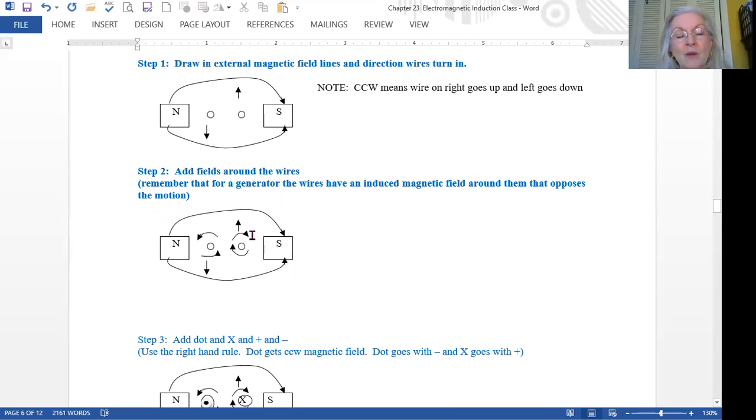The one I drew around the wire on just the top part also goes to the right. Like magnetic field lines would repel each other, and that would push the wire down. We know the wire goes up, so by drawing a field line that would push it down, that would resist the motion, we have our field line going in the correct direction.